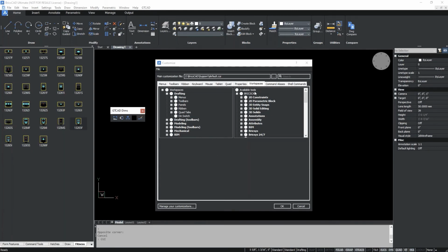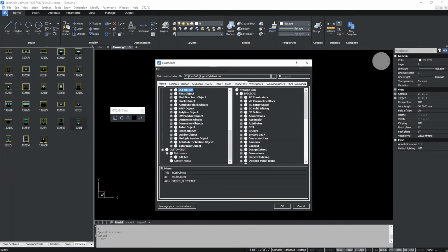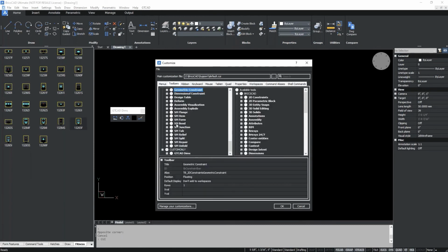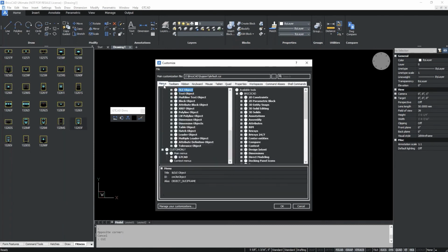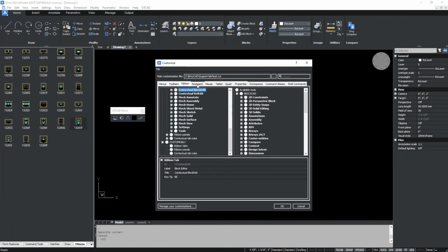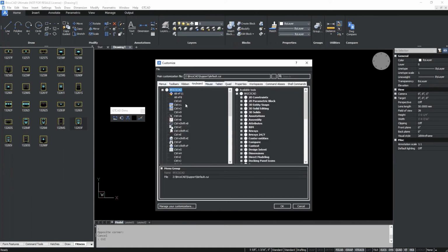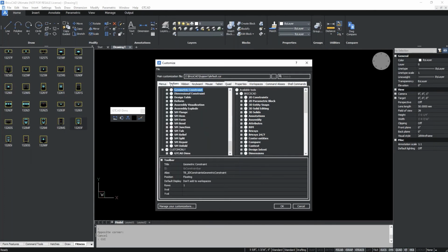So as you can see, it was smart enough to automatically paste it into your active workspaces. You can see that this was added into menus, this was added into toolbars, and you're getting an idea how our CUI dialog editor works. It's tabular rather than an indented long scrollable function. So it does look a little bit different, but it's very straightforward to use. If you can use the AutoCAD CUI editor, you can use this straight away. So I will say OK.